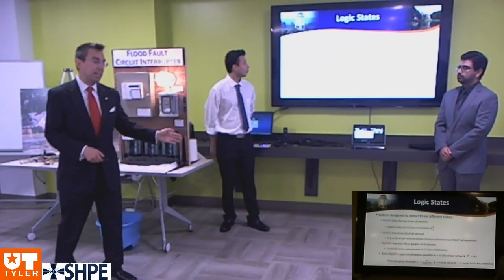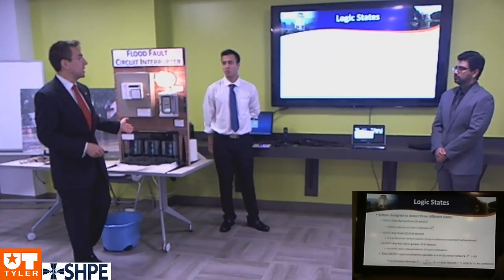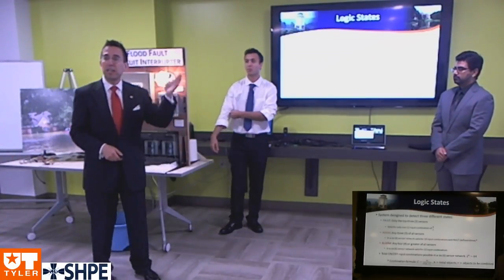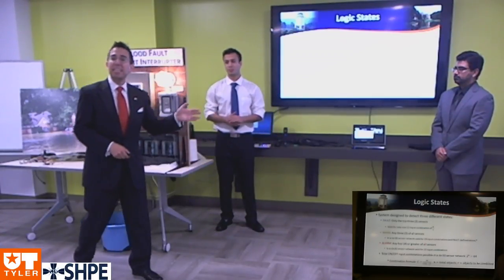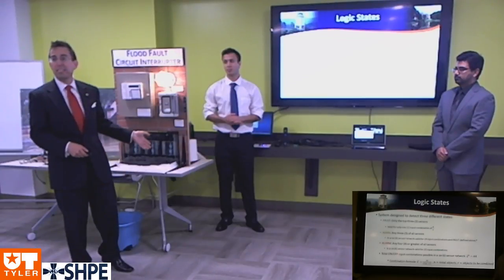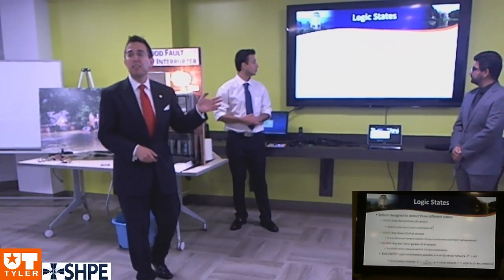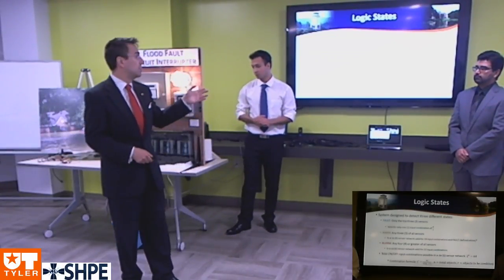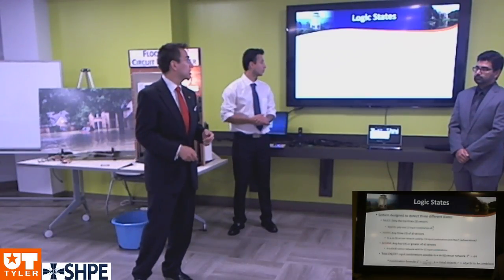The idea being if we have stacks of 2 sensors each, what if we only get back a signal from the top 3 sensors? So we defined a special warn state that would tell you that only the top 3 sensors are active. Then we defined a general warn state for when any 3 of these 6 sensors go active. And last, most certainly not least, we defined an alarm state in which, in this case, 4 or more of the sensors have gone active. The intention being, of course, that's the state that would indicate us to switch over to the electrical service.